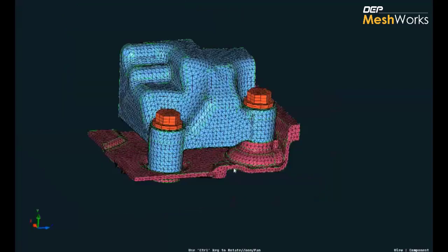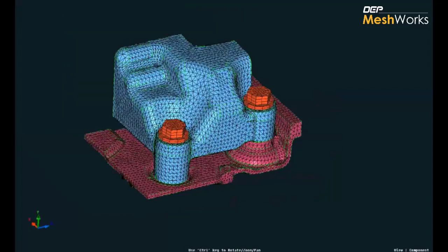Here I have now selected the machine modeling, and I'm just going to say generate a Nastran model. As the Nastran model is generating, I would like to also let you know what a solver attribute file is. A solver attribute file defines the type of element that we would like to convert. By default, MeshWorks utilizes a mapping table, and the mapping table is actually customizable.